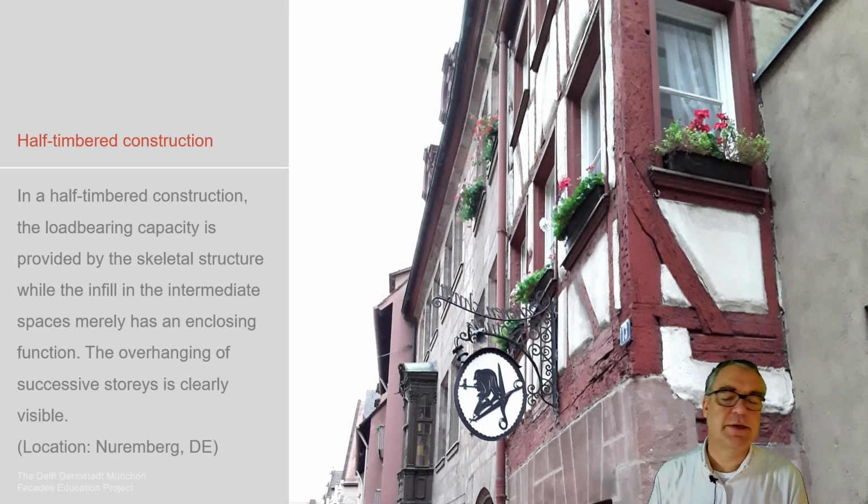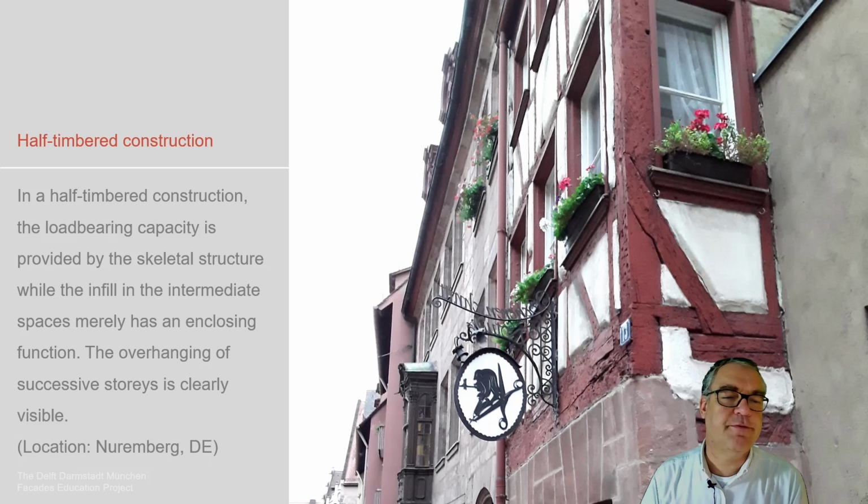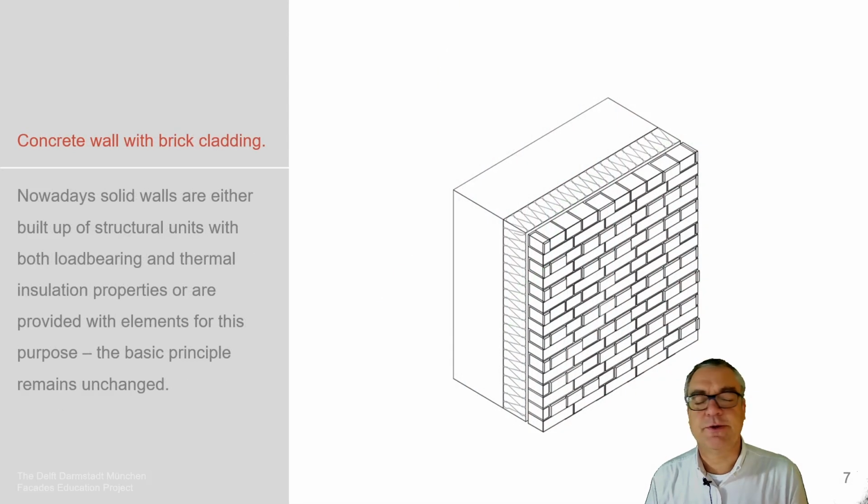Alternative way of doing is a stick system, timber stick system, done as a main skeleton structure, which we see here, the stick system as a structure, which is then enveloped and closed with this sample clay in the opaque areas and the windows in the areas where we like to have transparency in this system.